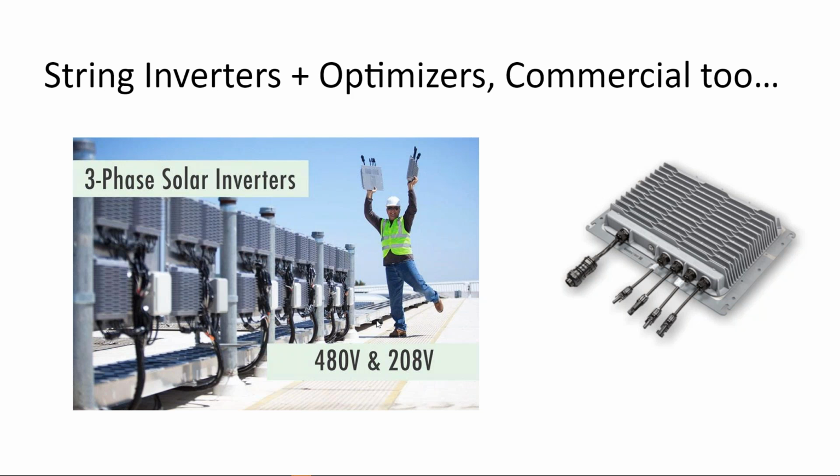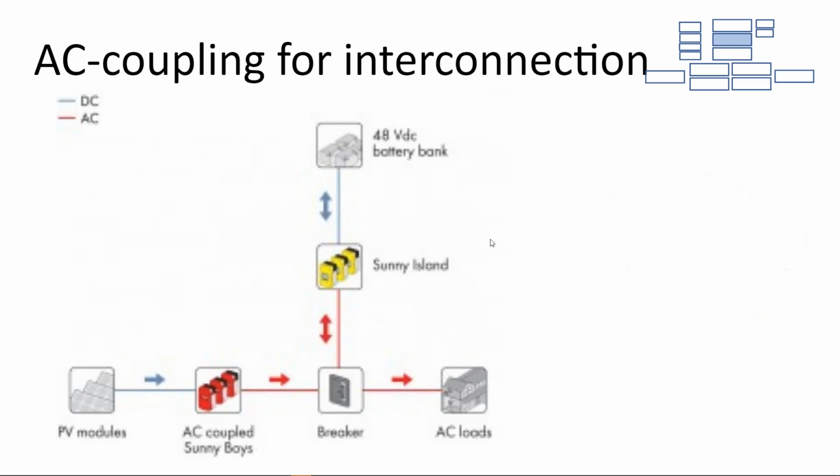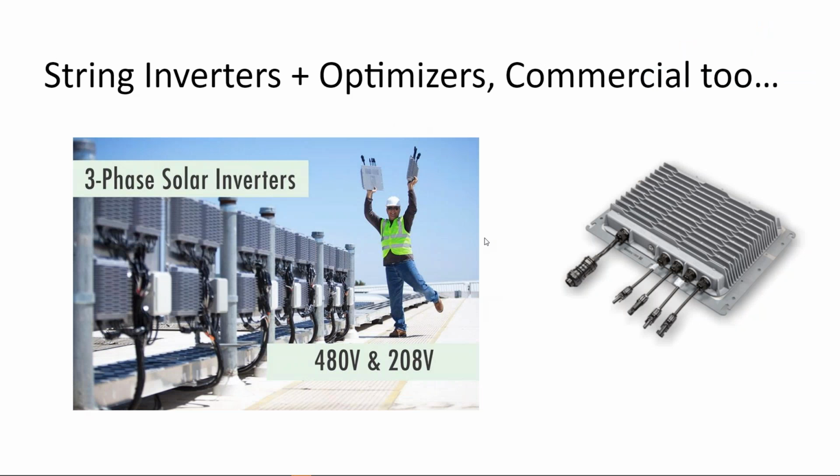This is just saying that they now make, even at the commercial level, little rooftop inverters to meet de-energize requirements. Right now, National Electric Code says you have to de-energize outside the perimeter of the array during a grid failure. Well, it doesn't have to de-energize; it needs the capability to de-energize.